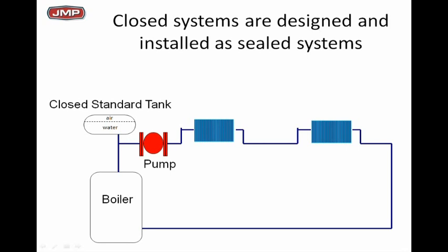And yes, that oxygen is going to go to iron oxide fairly quick inside that closed system. But if you don't add any more oxygen, what's left? What's left is nitrogen. Now, nitrogen is an inert gas. So now you've got a closed system. The only thing really in it gas-wise is nitrogen, which is inert. How long will that last? It'll last forever. And it really, really will if you keep them closed.